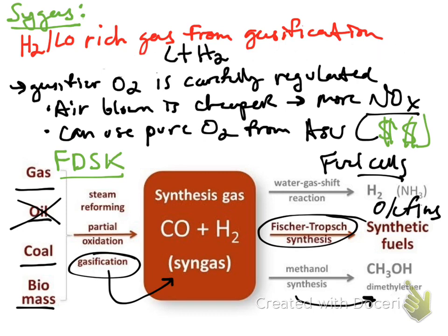And so here, I just wanted to write for you what that partial oxidation reaction looks like in its form. Carbon is reacted, and water is also present in these gasifiers. And usually the water is either blown in as steam, or it's mixed with the feed prior to gasification. That's generally what happens, and then of course you produce the carbon monoxide and hydrogen, the partial oxidation products.